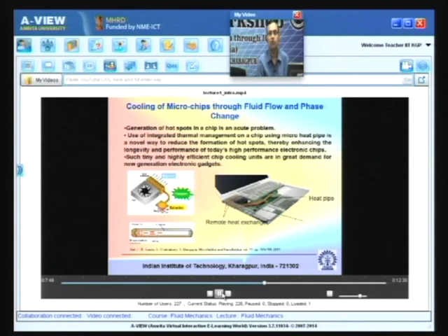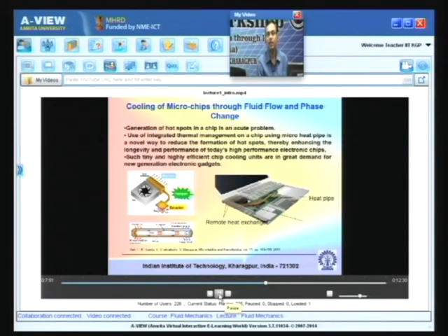We will discuss how capillary pressure can induce fluid flow in the later part of this introductory lecture, but this capillary pressure can drive the flow, and when the fluid reaches another place where the location is colder, it gets condensed. So, there is a cyclic evaporation and condensation taking place, and this entire heat is absorbed or released in the form of latent heat, not sensible heat, and therefore, there is no overshoot in the temperature. So, that is one strategy.